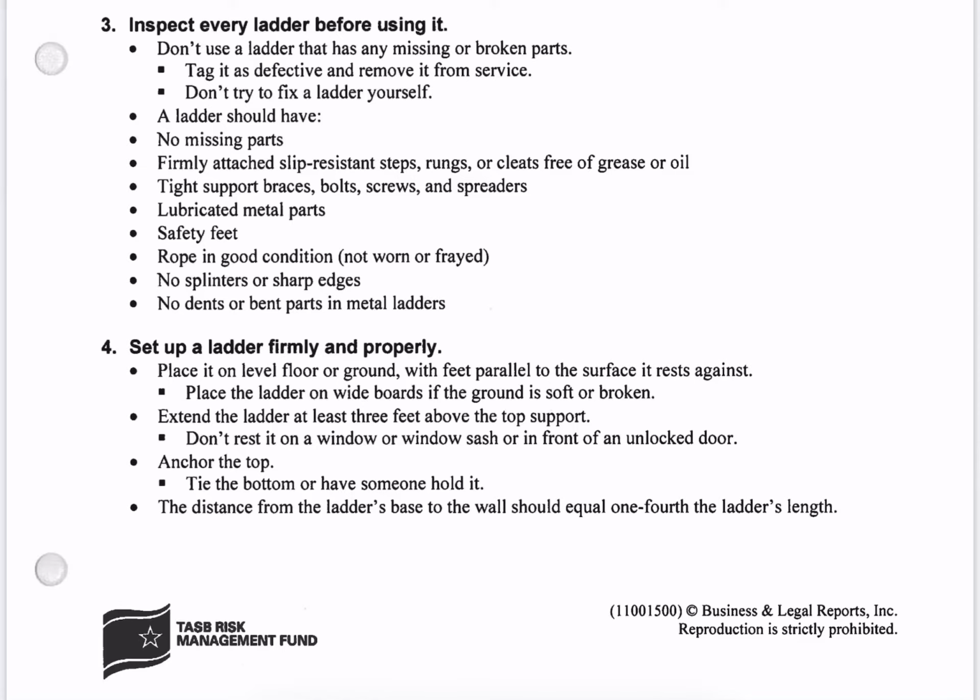Number 4, set up a ladder firmly and properly. Place it on level floor or ground with feet parallel to the surface it rests against. Place the ladder on wide boards if the ground is soft or broken.